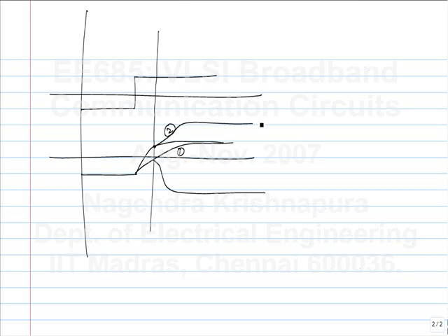Of course, there is a limit, because you are not simply increasing the GM when you increase the width of the transistor, you are also increasing the load capacitance. So, at some point it stops working, and also you are increasing the load presented to the previous stage. So, that may increase the rise time of what is driving the D inputs. If you assume a constant rise time for the D input, all this happens. But if, because you increase the loading to the previous stage, the previous stage is slowed down too much, then again this won't work.